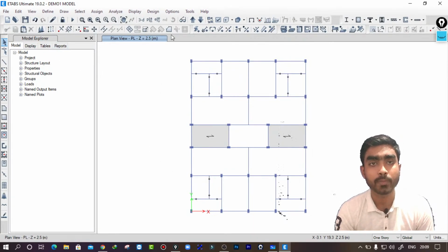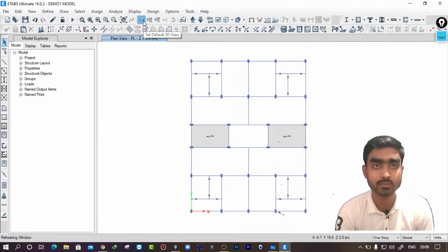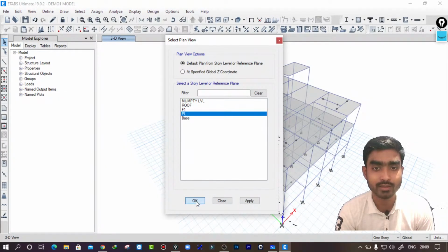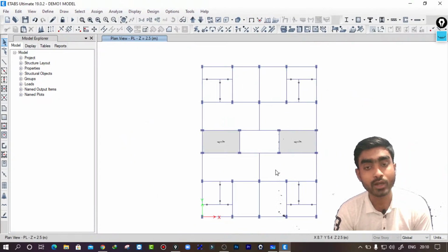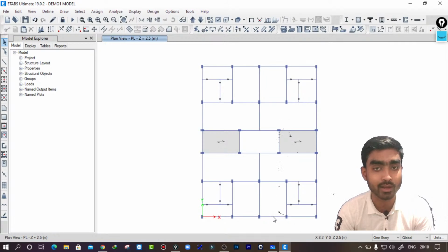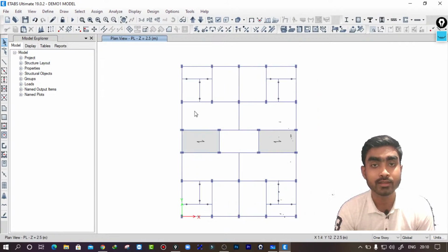Okay, so let's go to the top level. Here also, the diaphragm should be there, because in this part also you can have some movement, right? So if you want to give a diaphragm at this level, the floors are not there, but if you want to consider that here we have the floors and these floors will be transferring the loads to our vertical members, just for the sake of assigning the lateral loads, you can go with the joint diaphragms.